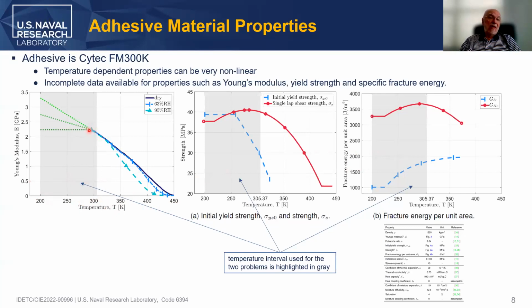So the last point we get is, as you can see, for Young's modulus here, and now we are faced with how to decide what to use in the model. We have two options. One is to extrapolate to the left, keeping a common tangent at the last point. Another, which is a little bit more conservative, is to take just a horizontal line. And a third one, of course, is to take something in between. Clearly, we need data here, but for the sake of the analysis, we implemented the one in the middle.